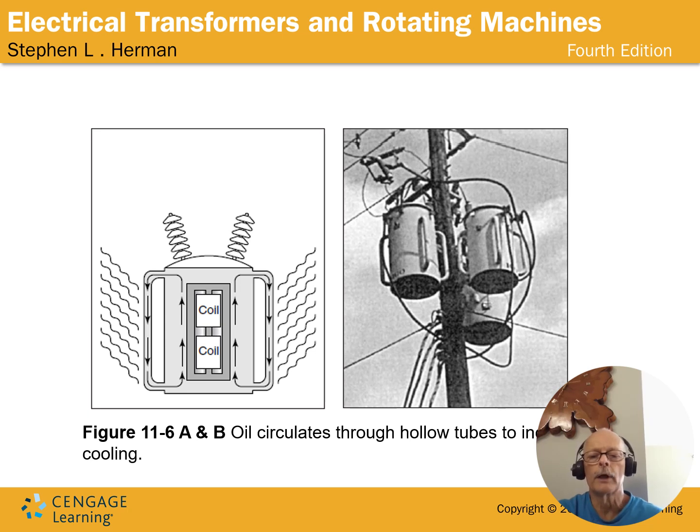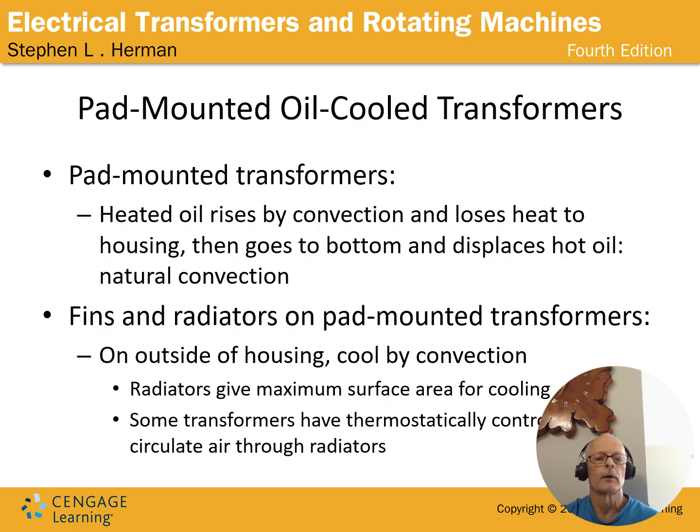Now these here, if you look at them, they only have one tube on each side, which are each four. It isn't four corners, but four quadrants. And so it's not doing that much. It's not circulating that much there, but that amount makes the difference that it needs to keep that transformer in its rated temperature.